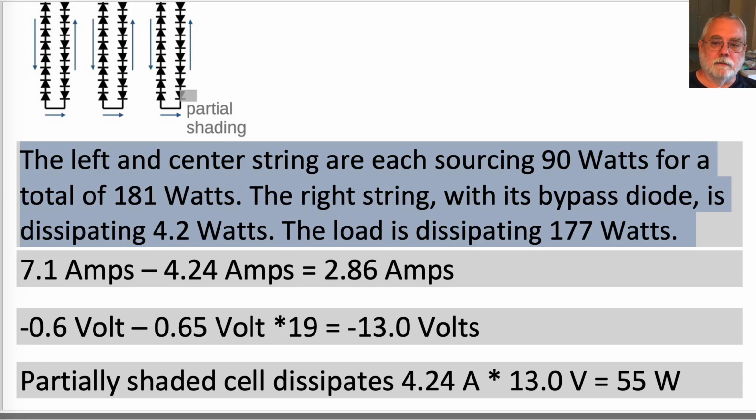This is a great result at negligible increase in cost and negligible reduction in reliability. The bypass diodes only help the system, and their help is independent of whether multiple panels are connected to a string inverter, microinverters, or DC power optimizers.